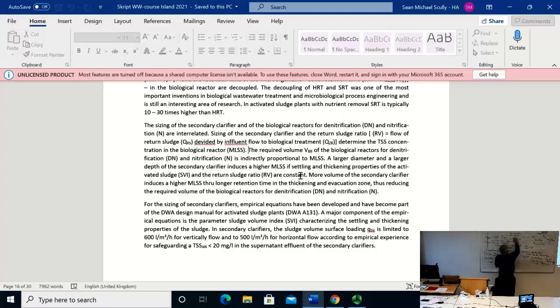that influences this design, it influences my retention time for the thickening here. Normally, it doesn't make any sense to make it much over 2 hours, because once I reach those 12.6 grams concentration, the sludge volume is very high, and the sedimentation velocity and therefore the thickening decreases, of course, the more sludge I have.